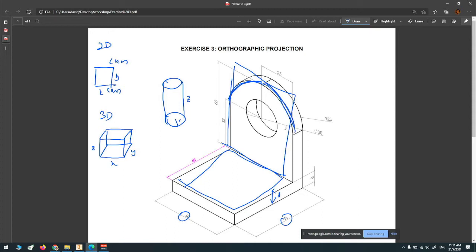After I add the fillet, I see that there's a hole over here, so I would have to make a circle somewhere and then tell the software wherever that circle is touching later, I want you to cut off that region. Actually, it would be best to flip it around, to do the cut first and then fillet. But for a simple component like this, it doesn't really matter. So let's keep it at that.